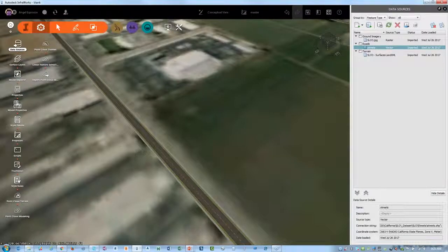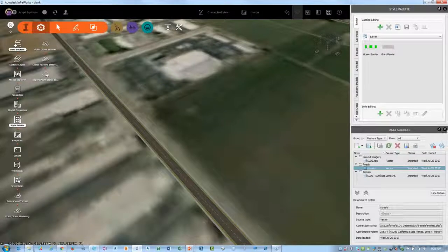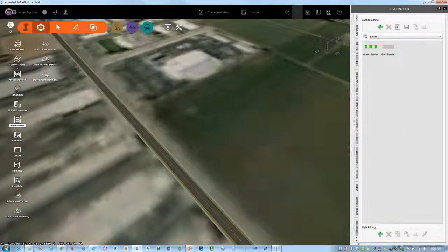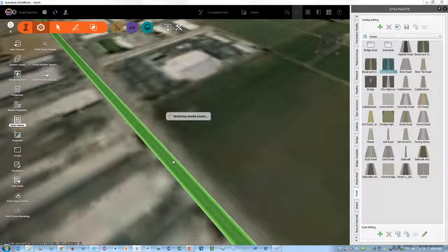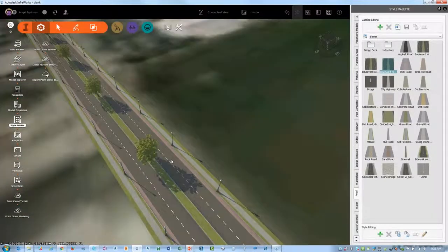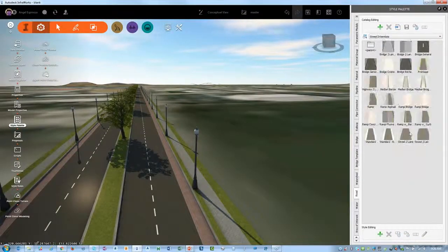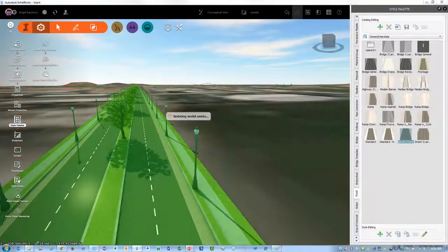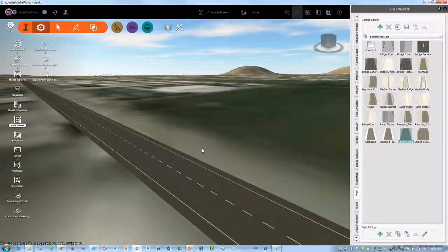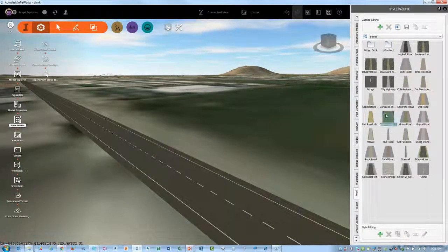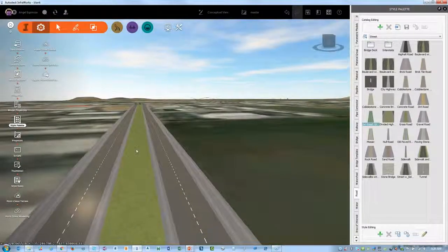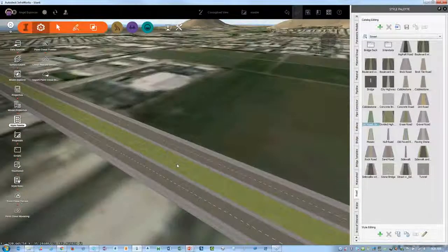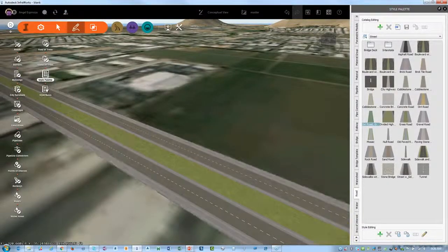One of the things I'm going to do is go over to the style palette here and look up the styles. I don't need my data sources any longer for roadways. And as I choose my different roads, you can see I can just drag and drop another type of road on there, and it changes that road altogether. So whether I'm talking about a 2-lane interstate, maybe with a small skip line down the center, or whether I'm talking about a divided highway, I can just drag and drop these styles onto objects, and I can replace different types of vehicles. I can replace people just as easily.